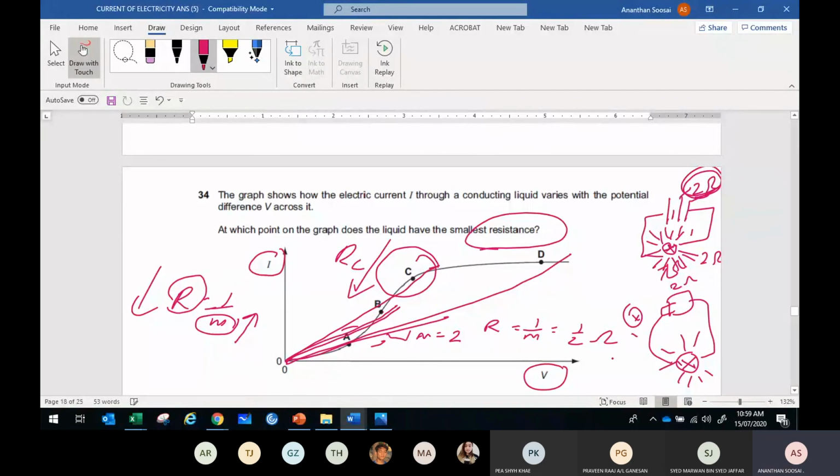Maybe the power rating of that light bulb is 20 watts, and the voltage maybe is 20 volts. So P equals V squared over R, and you find the resistance of this light bulb. We don't know what the internal resistance of the power source is. If both are the same, then you get the maximum power. So not every day will you achieve maximum power, because the 2 ohm internal resistance and the light bulb resistance are totally in the manufacturer's hand.